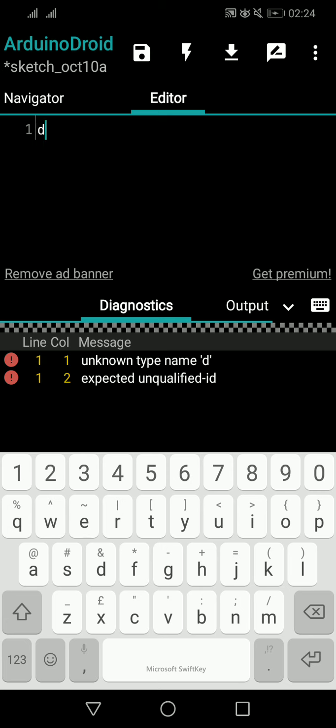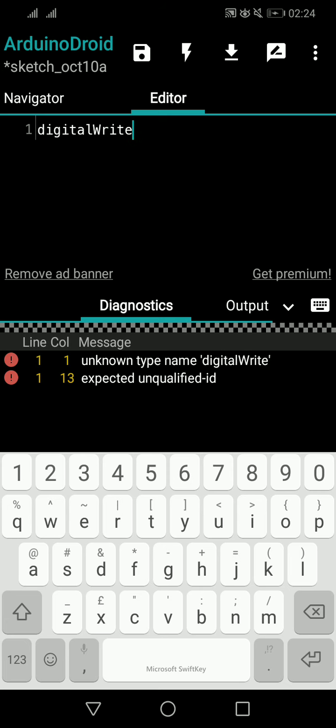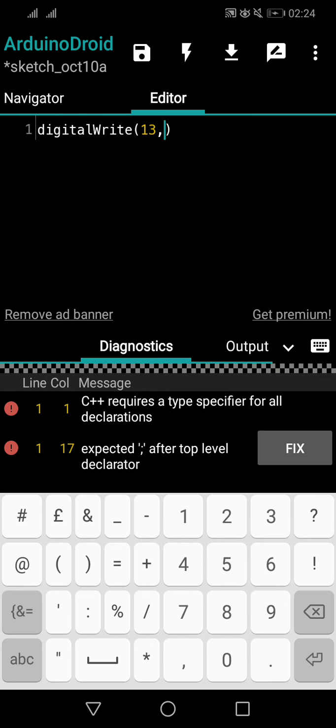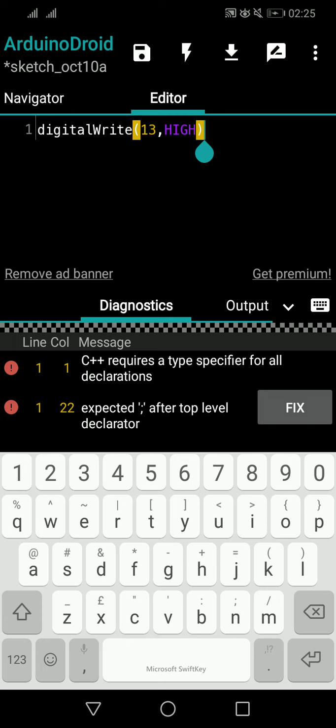Fundamentally, if you do a digital write to a particular pin, and you connect that LED to a pin, let's say 13, I'm just writing the line, HIGH. If you do it like this, then that means pin number 13 will get 5 volts. So there is full illumination of the LED, right? That means the LED is at its maximum brightness.